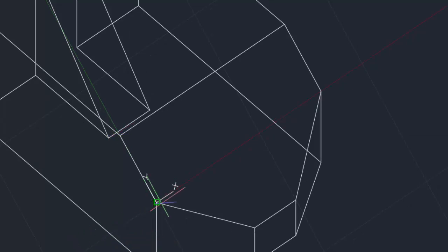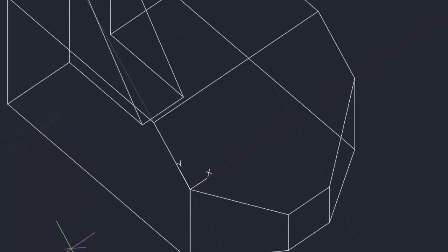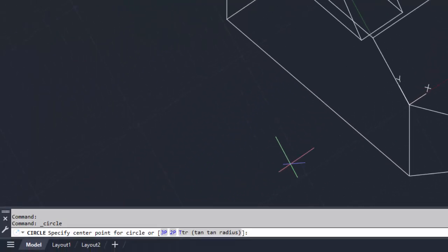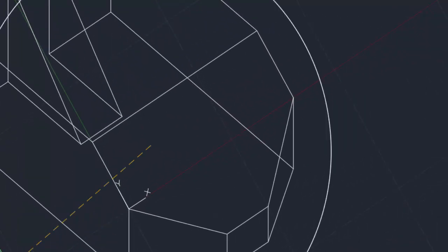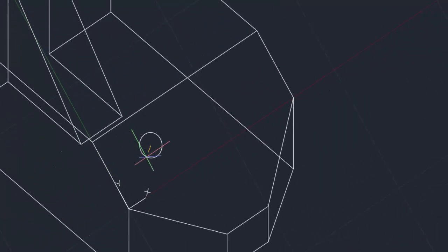And then because that is 0 and I'm measuring out from that point, I do not need the @ sign. So I am going to go 1, 0.75, so 3/4 of an inch up to there, and that's going to start where my drill hole is. If I do D and enter and 0.25, because that's the diameter I want, that's going to give me my first drill hole, and I could then move that across an inch and an inch to give me all 3.